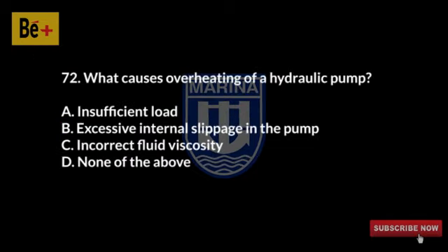What causes overheating of a hydraulic pump? A. Insufficient load, B. Excessive internal slippage in the pump, C. Incorrect fluid viscosity, D. None of the above. The answer is B. Excessive internal slippage in the pump.